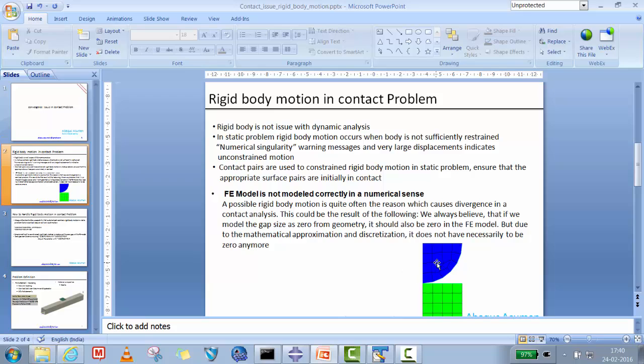And this is typically when you have one body applicator or two connecting bodies, the contact has to take care of unconstrained motion. And if there is even a small gap, Abaqus or any other solver starts throwing out errors: two unconnected regions, numerical singularity, high degree of DOF in a particular unconstrained direction. And guys, this is very important, how we can solve this type of issue.